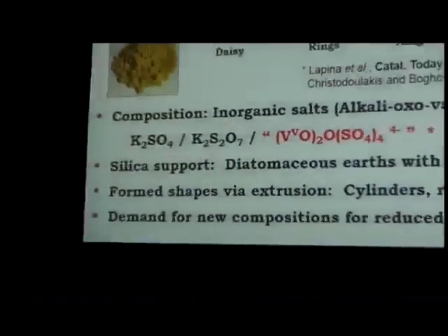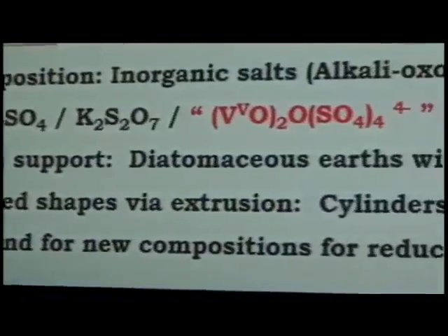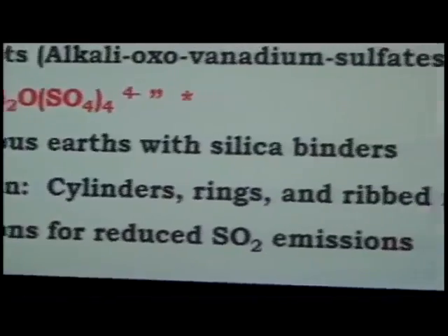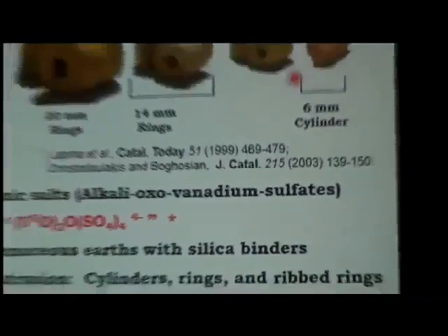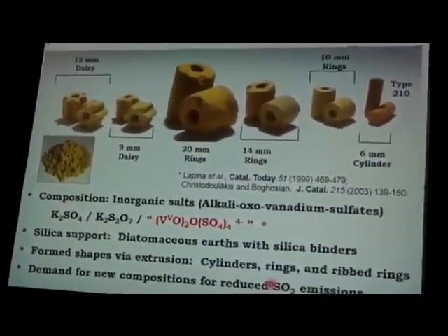Now, what's happened in this technology over the years, the shape has evolved. It's evolved for several reasons. Number one, they want to obtain particles that have a higher activity, which means you'll have reduced SO2 emissions. But they also want particles that result in a reduced pressure drop. Turns out those are two counterposing things. We know smaller particles in general will give us a higher pressure drop, but also improved activity. So the game has been to figure out how to add these lobes and other types of artifacts on top of regular shapes in order to increase activity while, of course, minimizing the pressure drop.